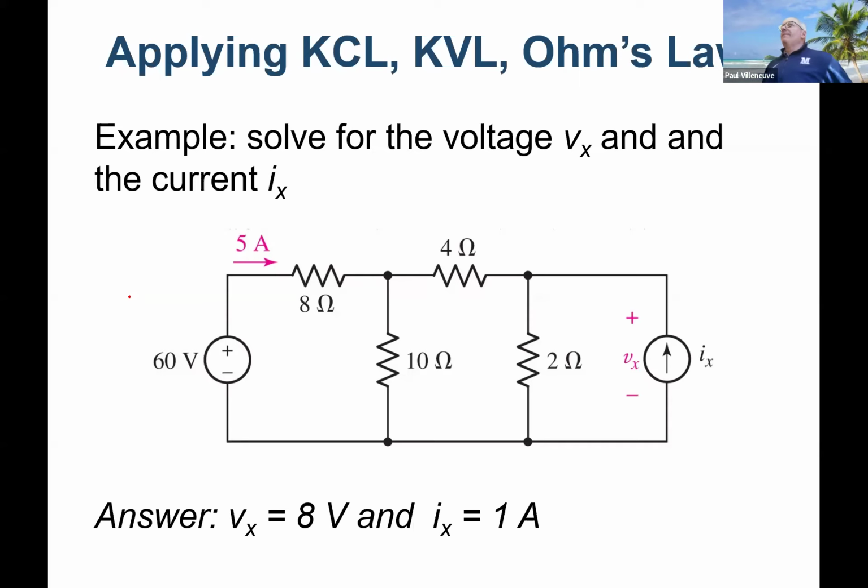Luke? Find the voltage drop across the 8 ohm. Yeah. If I can calculate this voltage drop, don't I know that voltage here? So what is the voltage drop across the 8 ohm resistor? I times R, or 40 volts, right? And it's in the direction shown because we know that a resistor is always a load. That's never going to pump out electrons, right? That's always dropping. So now I have 40 volts.